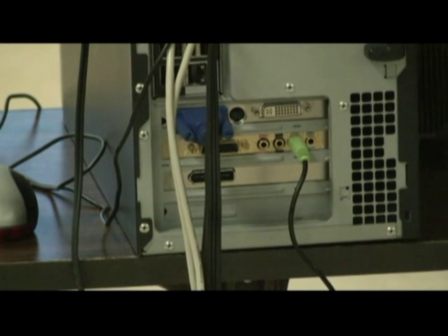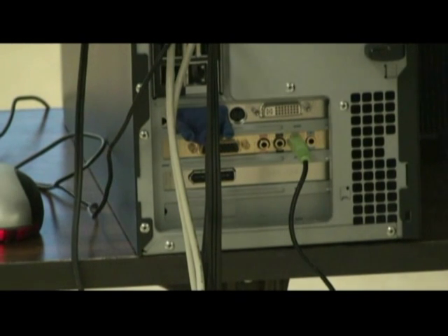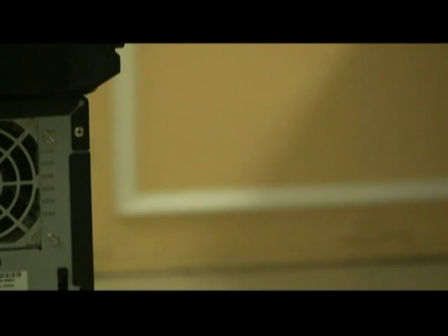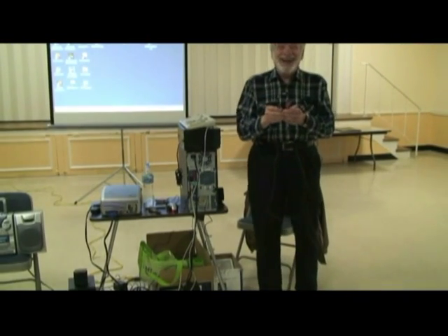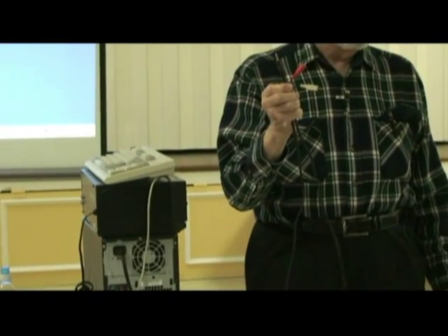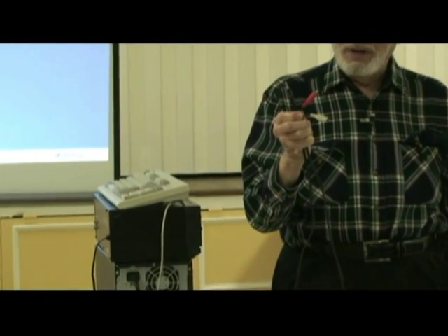So here's what you have to do once you locate that jack. If you only have one, you're going to be plugging into that one jack. If you have two, one that says microphone and one that says line in, you want to go into the line in. Now, what do you go in with? Here's where you're probably going to have to visit your local Radio Shack. I think it's cheaper there. Pick up a cable like this. This is a mini plug, a stereo mini plug on one end. And I guess for my purpose, I need to hold this still, don't I, honey? And RCA connections on the other, which they've standardized today as red and white.